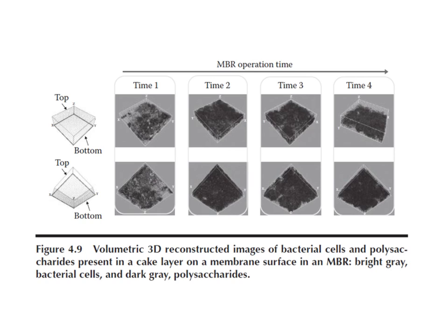Using CLSM, we can have information at different positions, and we can also have information at different times. So, for instance, if you monitor the biocake on the membranes in an MBR during some period of time, we can see how the biocake evolves and develops during the MBR operation.